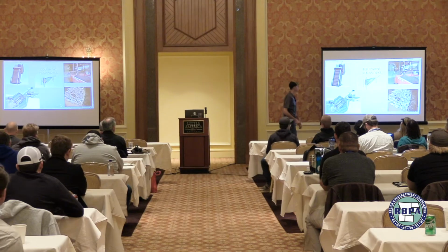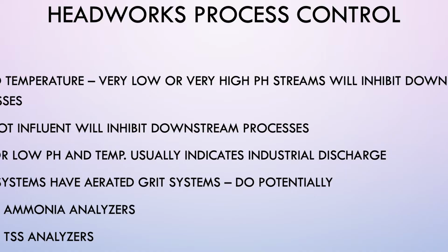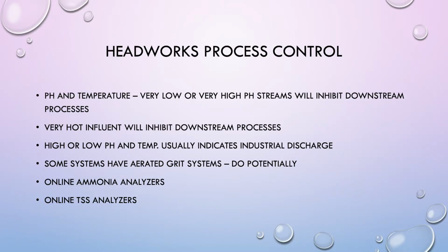Headworks equipment. Let's go back to the front of the plant just for some visual stuff. Step screen, rotating perforated plate. You've all probably seen one of these. Grits and rags. You've all seen that, right? Part of your job is to make sure that we don't get too much of that. Headworks process control, just normal stuff, right? We want to make sure of the same thing you in the pre-treatment world are worried about: no weird pH swings, no temperature swings, no big stuff, no oils, no greases, stuff like that.